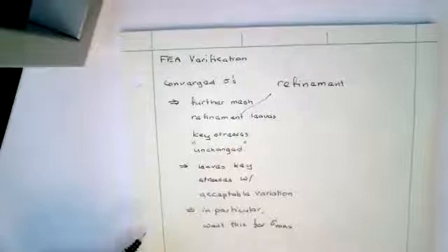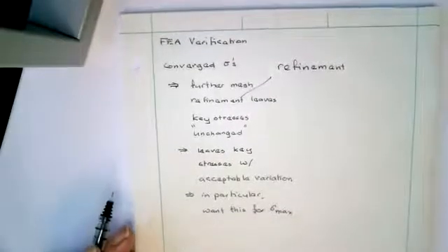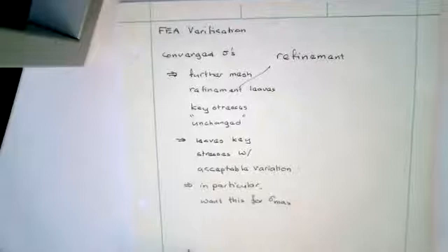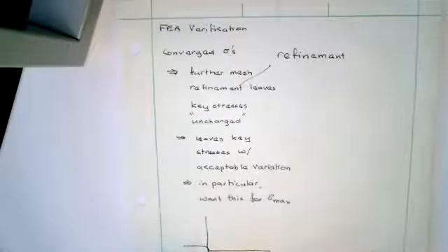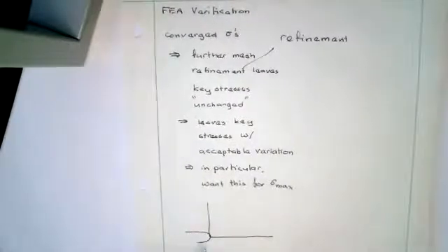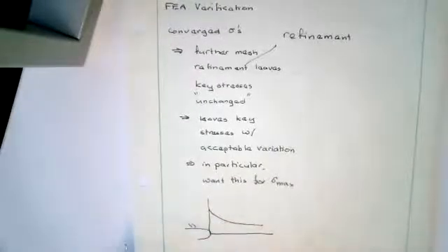What's going to tend to happen is away from the peak stress, the stresses will converge pretty well, but at the peak stress, they won't converge as well. So if you have some sort of hole here, the peak stress looks like this and reduces as you go out.